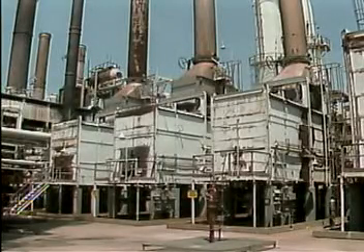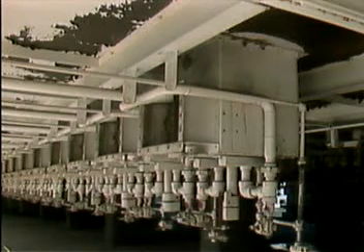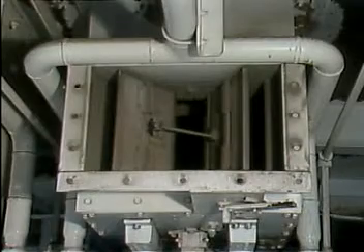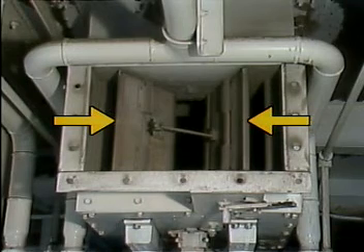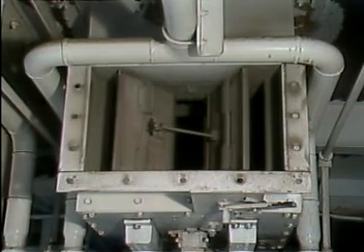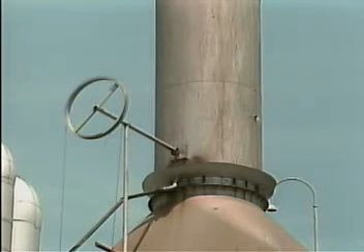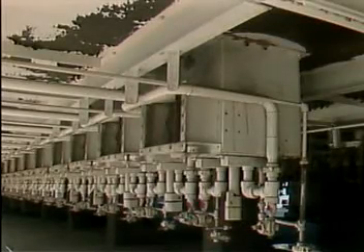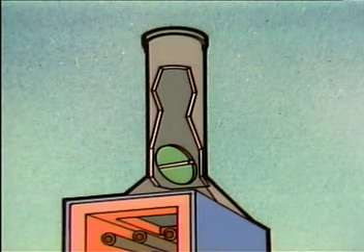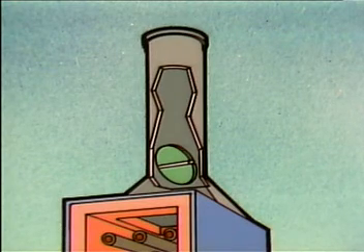Furnaces also need air systems. An air system is needed because the burners in a furnace mix air with fuel for combustion. Airflow to a furnace can be controlled in different ways. For example, on some furnaces, airflow is controlled by registers and by the stack damper. Air is drawn into the burners through air registers. The registers can be opened or closed to let more or less air into the burner. The stack damper is used to control the flow of gases leaving the furnace. This also affects the amount of airflow that can enter the registers. Opening or closing the damper increases or decreases the amount of air that flows into the furnace.